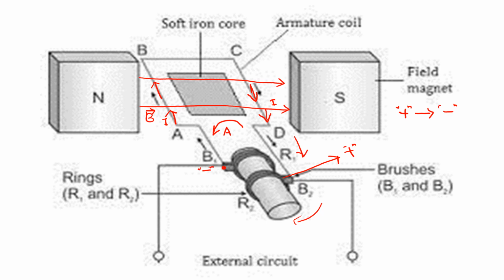So now, since you know that the armature rotates either anti-clockwise or clockwise between the permanent magnet, we consider that it is rotating anti-clockwise. So initially, if it is at position C, if the armature rotates anti-clockwise, then position C will come here, whereas position B due to rotation will come here. So this means that position B will change into a positive terminal, whereas position C here will be converted into a negative terminal.